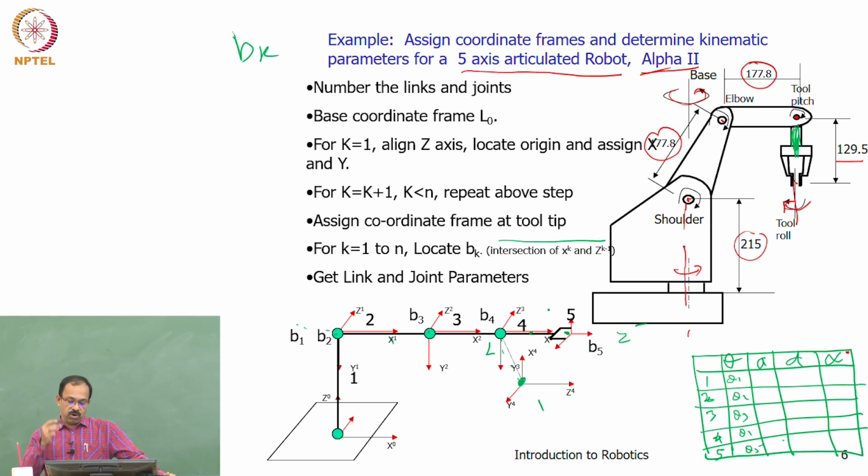So why I am saying is that our whole aim is to get a relationship in terms of theta. So this need not be considered as an offset, because this offset depends on how you actually assumed it. So for home position, you can say it is 90 degree in this case. For the time being, I will make this a variable, and I assume that there is no need to calculate the value per se, because it's a variable in any case. For different configuration, you will get different values of theta. So I don't really worry about the current value for this home position, because this is just an arbitrary position I have taken. Therefore, I am not really worried about the actual value now, but if I want, I can find it out, no issues.